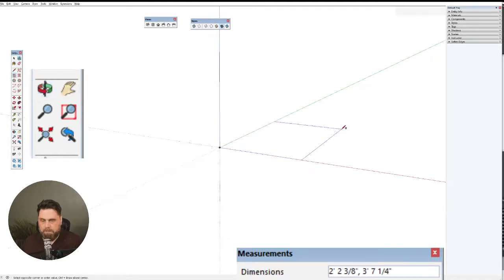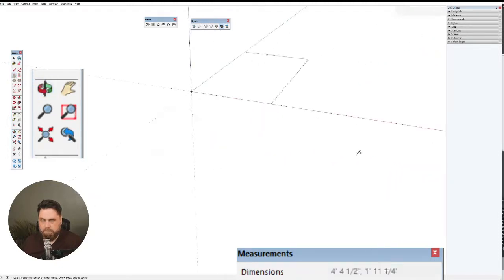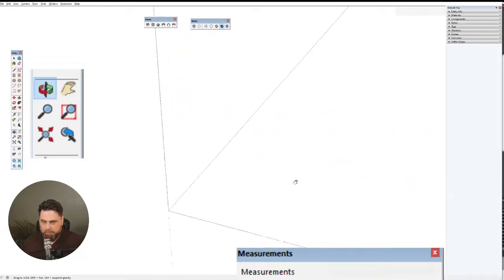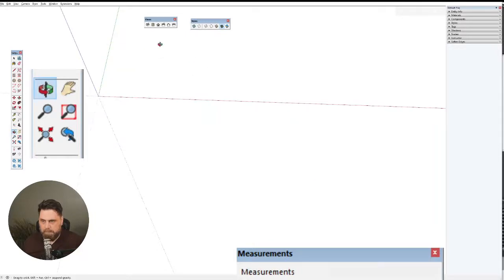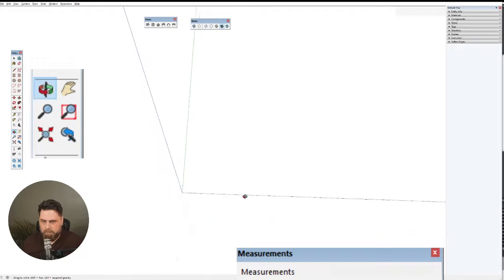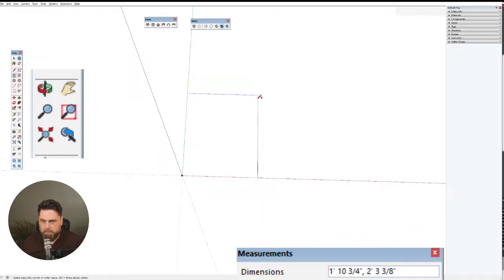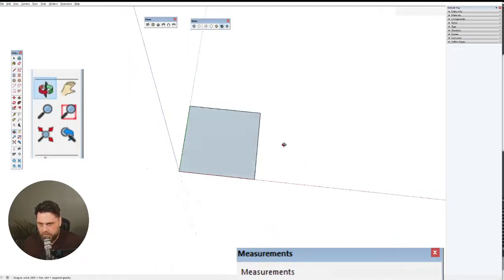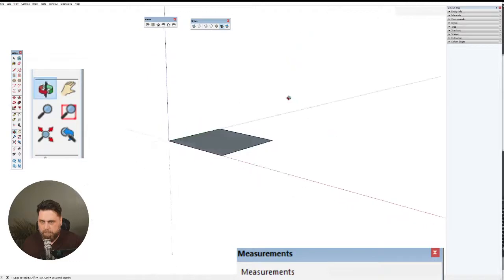And this might look square, but if we rotate up, and we do that by holding the middle mouse shift to move down, and then let go of shift and then rotate up. Come back and grab it again, middle mouse shift, rotate down, let go of shift, and then rotate up. Now we can kind of see that showing up when we're square. Let's just click there. Then we're going to rotate back around with middle mouse button.